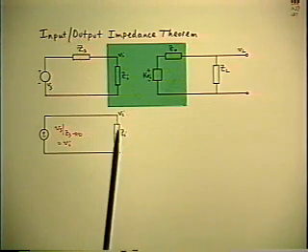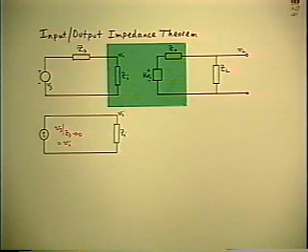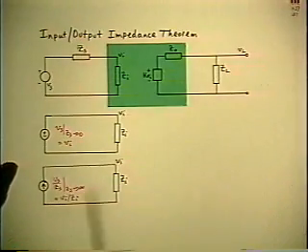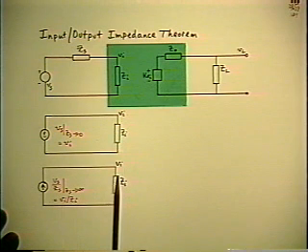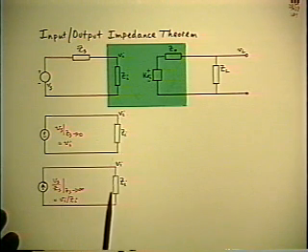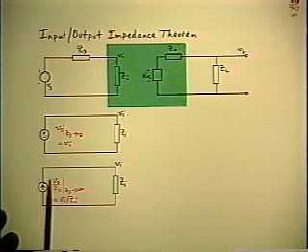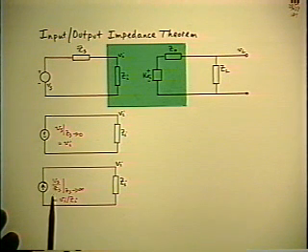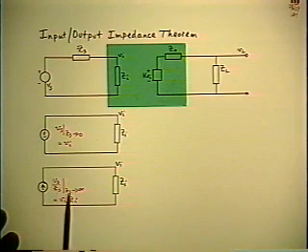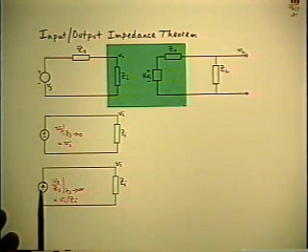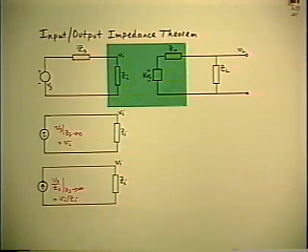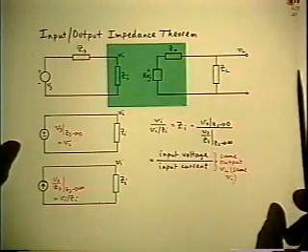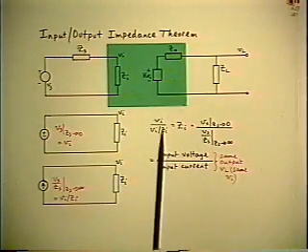Then let the parallel Zs go to infinity and ask, what current do you have to apply from the Norton source in order to get the same voltage at the input to the system as before? So the value of the Norton current that you have to apply, Vs over Zs, under conditions that Zs now goes to infinity, the current you have to apply is obviously equal to Vi over Zi. And you divide one answer by the other, and the VI's cancel,